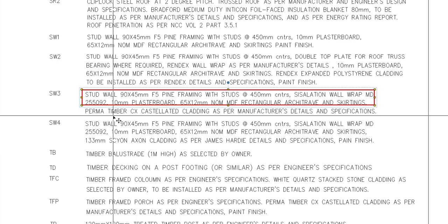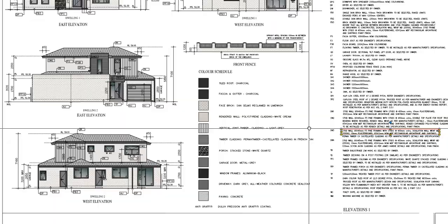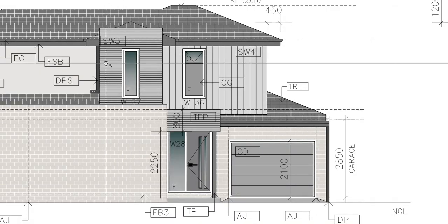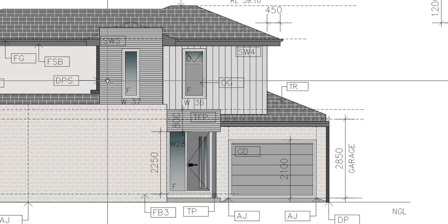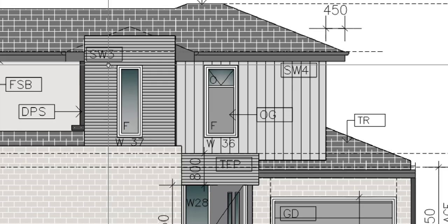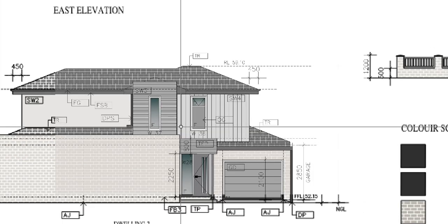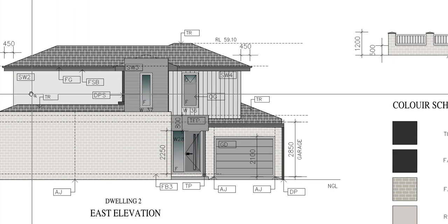You just go there and check how they are installed, if battens are needed. Sometimes these claddings need battens in the front, and they are installed on battens. So you take the extra batten, purely depending upon the installation guide by the material provider, whichever material you are using.